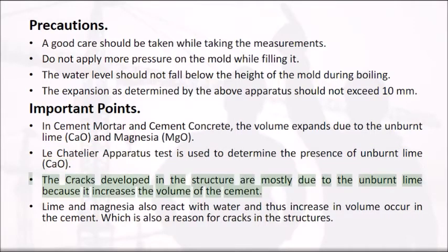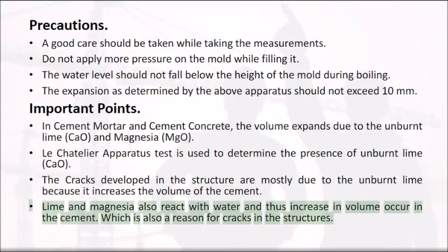The cracks developed in the structure are mostly due to the unburnt lime because it increases the volume of the cement. Lime and magnesia also react with water and thus increase in volume occurs in the cement, which is also a reason for cracks in the structures.